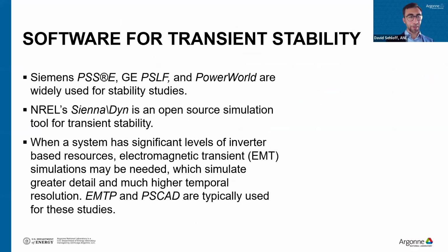This is a much more complex and computationally heavy study. But it's necessary in some cases, especially with a lot of PV or storage or other types of inverter-based resources. So EMTP and PSCAD are great softwares for those studies. Next slide.